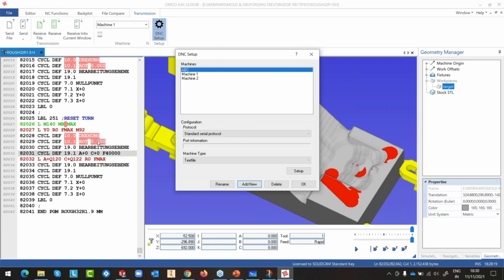You'll see a handshake happening on the controller. Just below the place where you have got the access information, you will see a blinking happening that it is receiving data from the DNC. And once it receives enough data, it will show up in the NC memory. It will show the program with all the blocks that have been received, and you start your machine, and the computer will start drip feeding as and when the blocks are emptied on the machine.